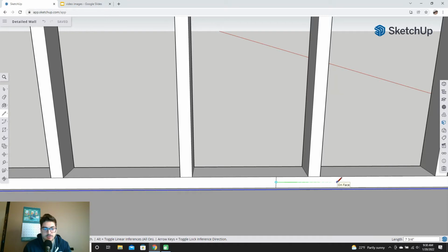That takes up an average of 2 inches, and whoever's hanging your door is going to tell you, well, it's a 32 by 80 door. And a real framing person who knows what they're doing is going to add 2 inches to both of those for the rough opening. So there's my spiel about doors.